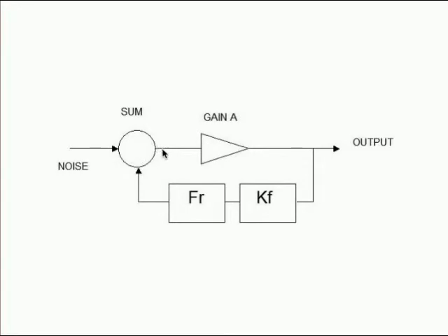Right, so this signal here is not just the feedback, it's actually got the noise in it as well. The noise in a practical oscillator is going to be very small compared with the feedback signal, but nevertheless this signal here is not just the feedback, it's got noise in it. To consider what the loop gain actually is, the loop gain is the ratio of these two signals.